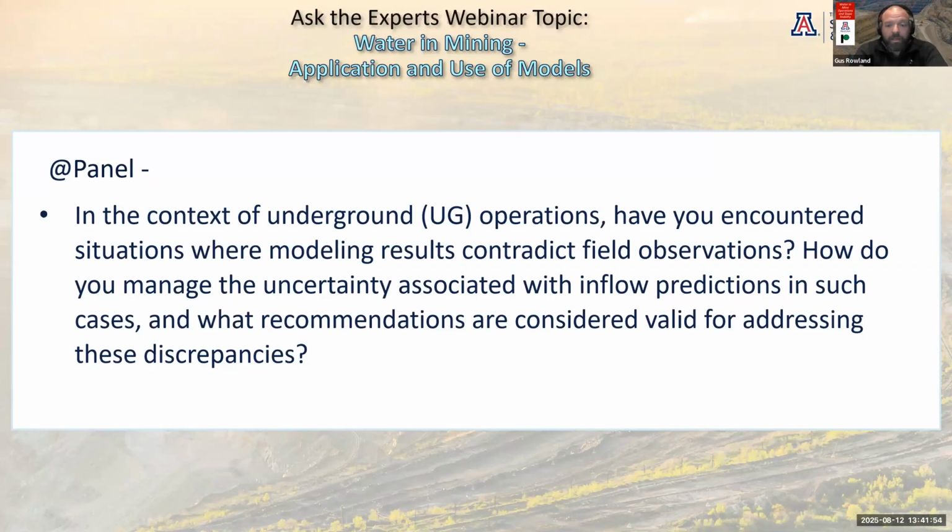And so making sure that your modeling team understands what question they're trying to answer is really important. And so often, as Travis mentioned, the characterization is so key. Understanding things like instantaneous yields and blow yields and expected average strike yield from things like cover holes is very important to make sure that you're sizing pumps and infrastructure adequately, so that you're able to deal with rapid inflows of water if they might happen.